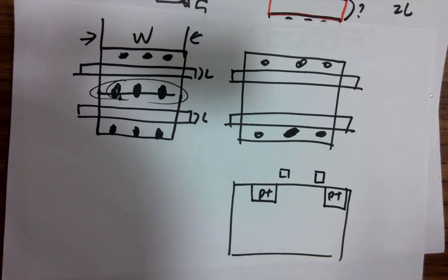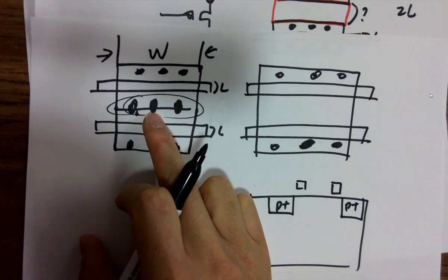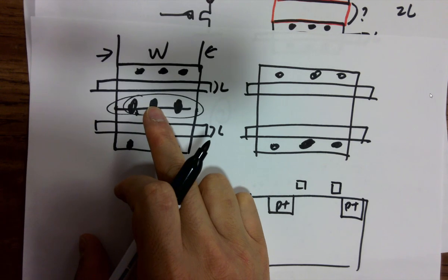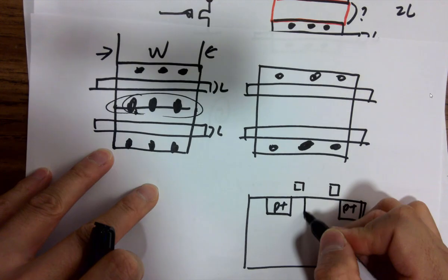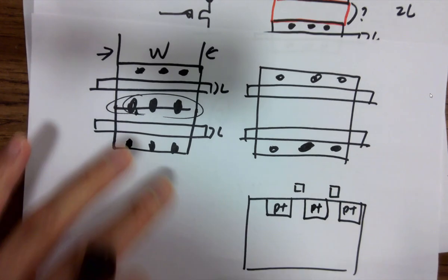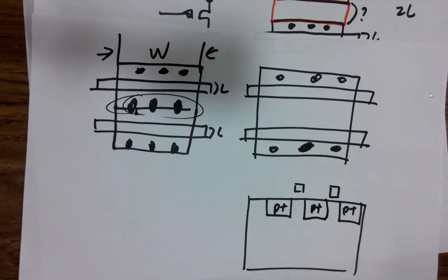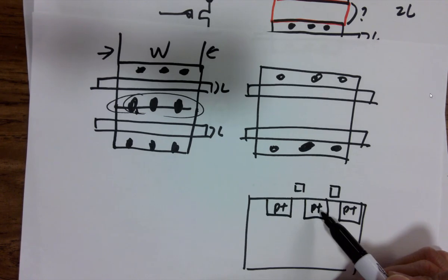So for this guy, you got a P plus in the middle. I think you still have P plus in the middle, but just no via and metal one. That makes sense. So just ignoring this P plus, it's just treating this guy as an ideal metal piece or something, right?